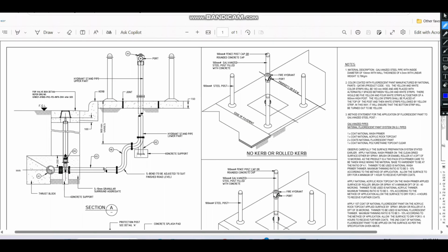So this is one of the very important drawings related to the fire hydrant system installation. This is the main pipe. In our project it was 200 mm dia. From the 200 mm dia, we are making the branch with 150 mm dia. As I told earlier in the isolation valve installation, this is the flange adapter, and we have the isolation valve here. We have the 150 mm PVC tube, and this is the surface box we can access from the top side.